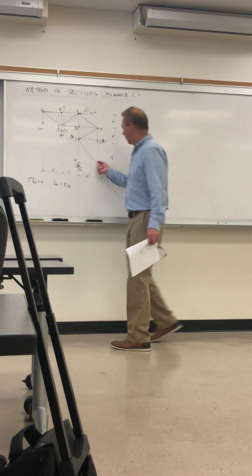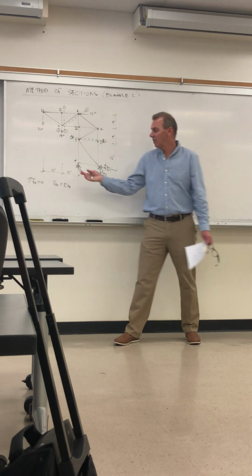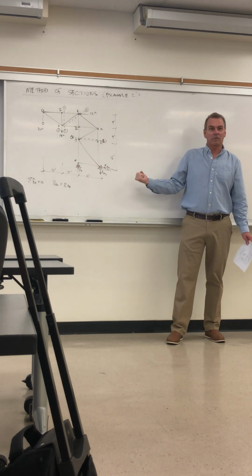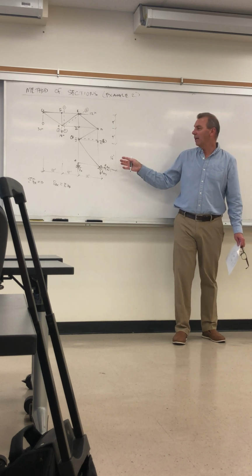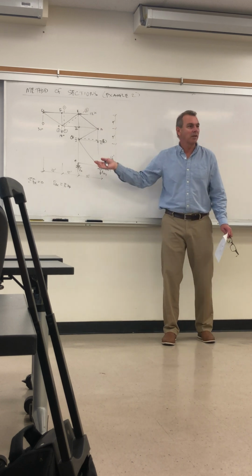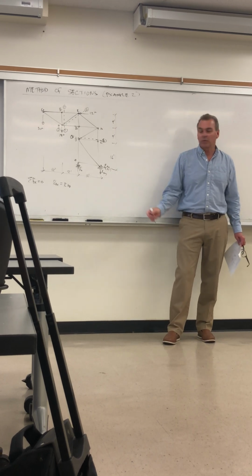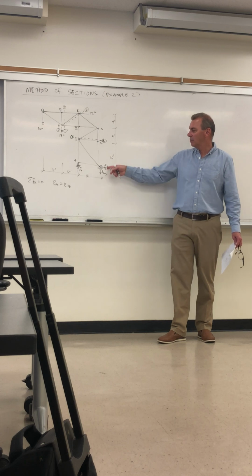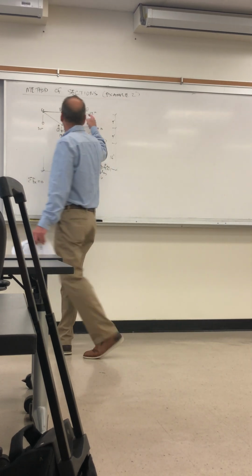If we didn't have a pin here holding us back, this load is trying to push the structure that way. This pin is literally stopping it, with no movement at all at that location, and only slight deformations throughout the structure. It's preventing the whole structure from moving dynamically. So that's 12 kips this way; the structure feels this 12 kips pulling that way, and it feels 12 kips pushing that way.